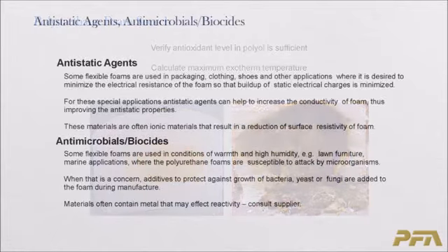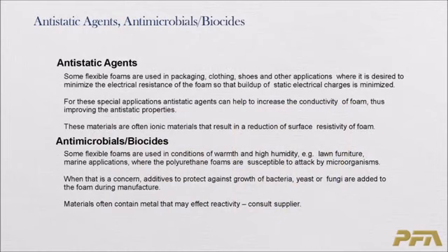And lastly, there are a lot of other additives, like anti-static agents if you're trying to make some special type of foams for, say, clothing or shoes. If you're trying to make foam that's used in warm, humid conditions, like outdoor furniture, you may want an antimicrobial or biocide. There's a whole variety of different types of additives, and again, like a lot of these things, these additives can affect reactivity. So you need to verify what that reactivity is on a small scale before going into production with it.